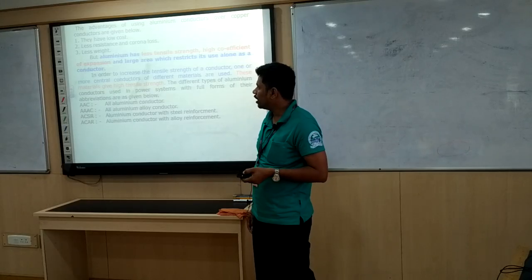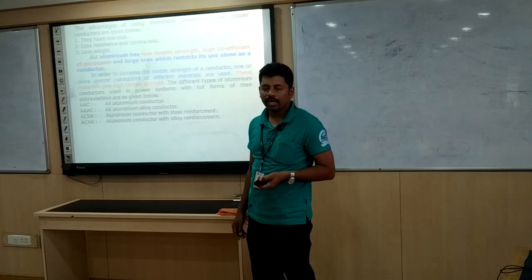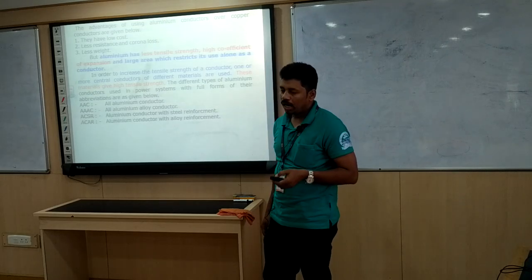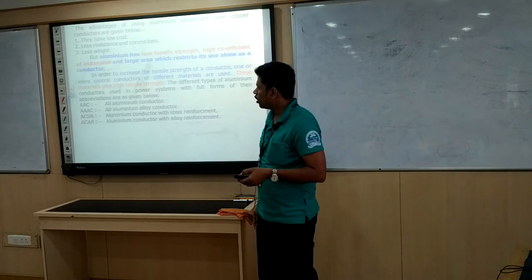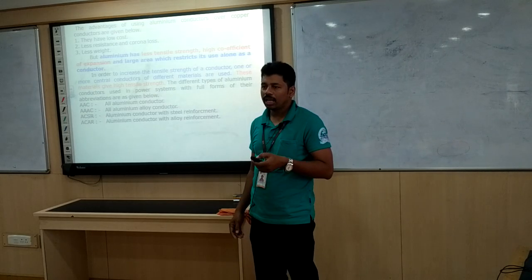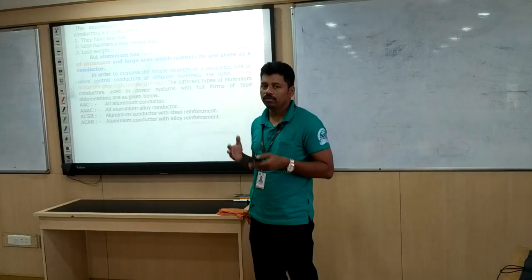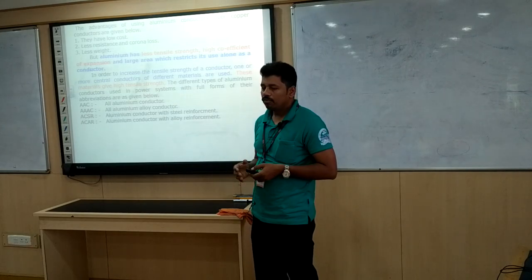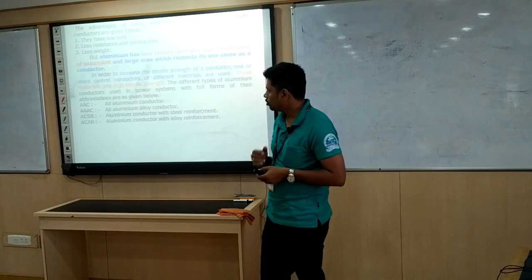Less resistance, less corona loss and less weight are the advantages of aluminum. Not only the cost, the total weight of the aluminum is less, so the amount of support you need to support the entire transmission line is also reduced.